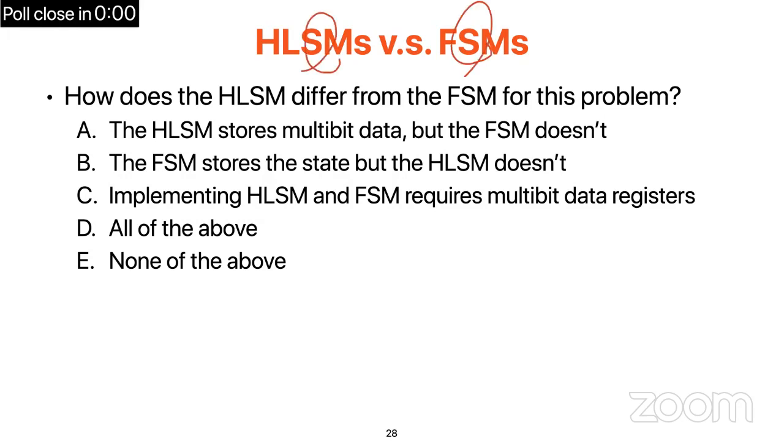And all high-level state machines decompose to a finite state machine. It's just if you drew them as finite state machines, they'd be basically illegible. Because with multi-bit data fields, you could just write truth tables for everything. It's just the truth tables would be way too long to even print. That's why we don't use finite state machines in these scenarios, because we're handling too much information to represent every single last combination. We've got to start grouping things logically.